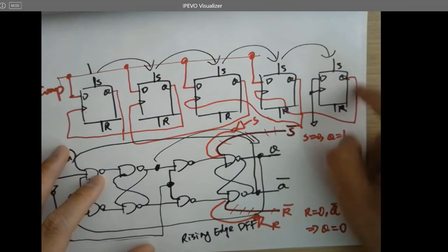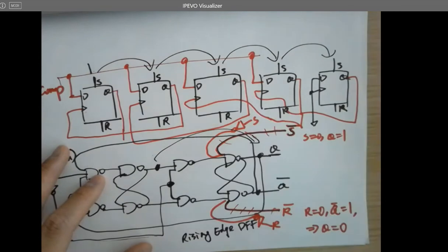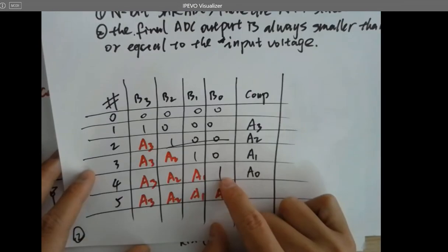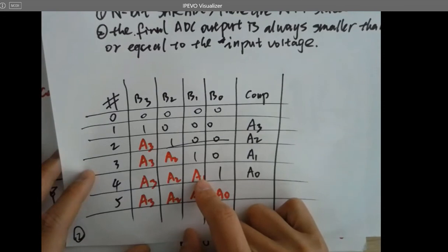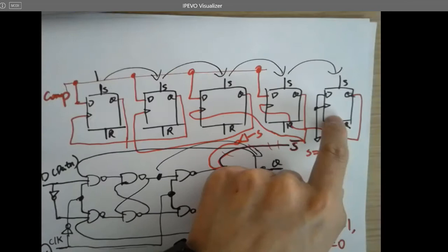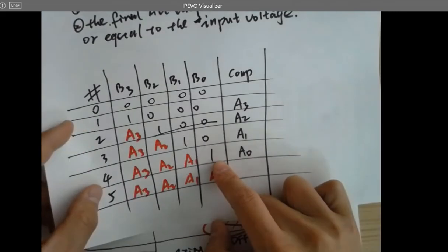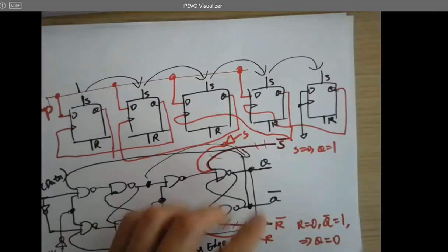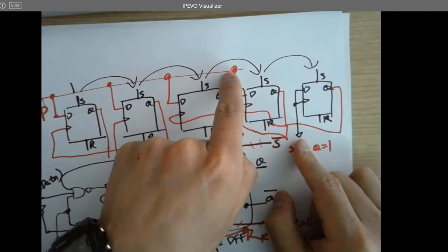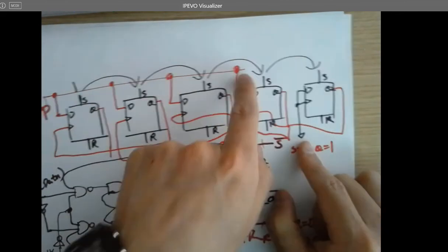Yeah, I need a rising edge to the LSB, because eventually I still need to set this guy and plug in A1 to the previous stage. So this guy is doing this job, because this one was being sent from here, and I do not need this D to be shorted to comp, because I do not need this guy to accept any comparator's output.